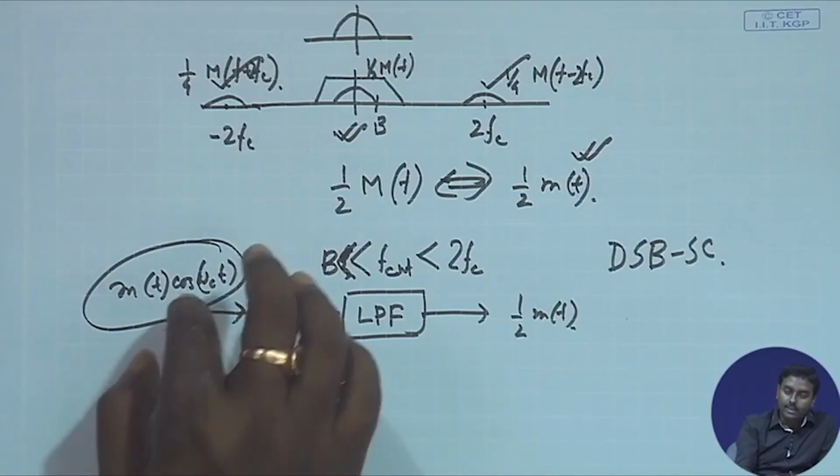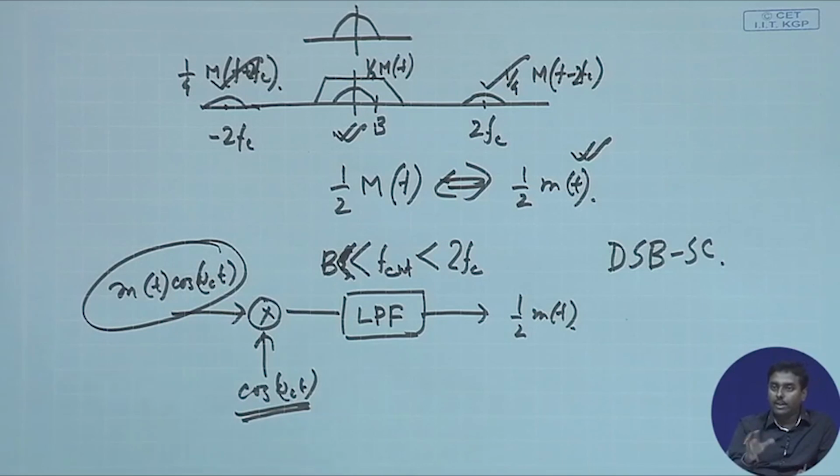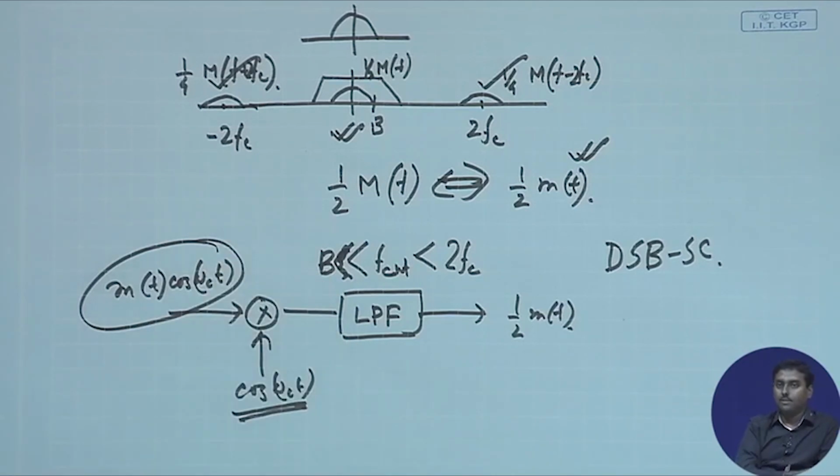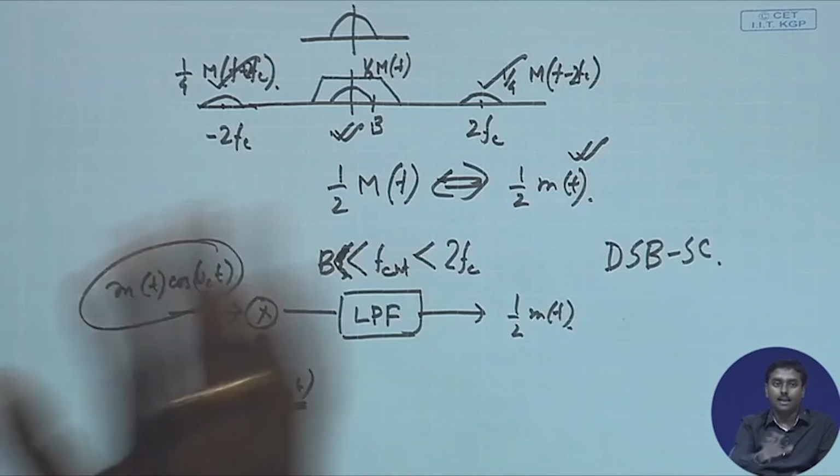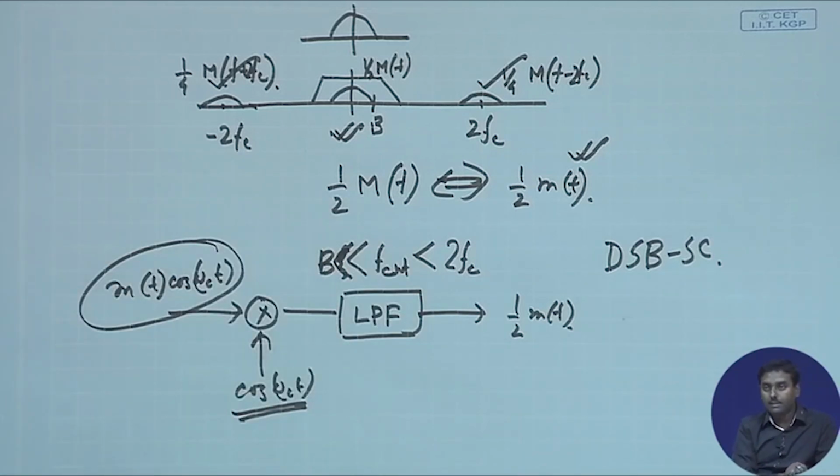So, what I generally have to do is this: the signal that I am getting already has, of course, a contaminated cosinusoidal. Can I extract that carrier out of this? If I can do that, and from there generate this cos omega ct, then I am fine. That is called carrier recovery.